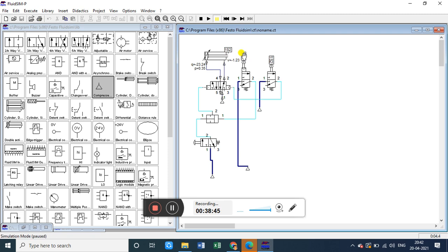Now because of this, what will happen, the piston will come back to the left side from the right side. Means it will move from this position to this position. Means it will come to the 1:1 position, so it should get pressed, and this should get unpressed before pressing of this 1:1. So I'll make these changes. So you can see right now the supply is for this side. Again I'll go to this. Now the 1:1 will get pressed whenever the rod is coming to this 1:1 position. That's it.